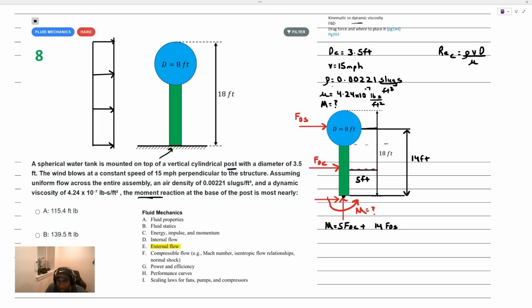You could see that in the problem, when they mention the units here, they just put pounds, and that's pretty common. We don't always specify whether it's pound force or pound mass, but if you think back to Newton's law of viscosity, shearing stress is equal to mu du dy, and I usually like to think about things I don't know the units for in terms of their fundamental equation, which is this. We know that the shearing stress tau is pound force per foot squared, but typically it's pound per inch squared, like a PSI or KSI.